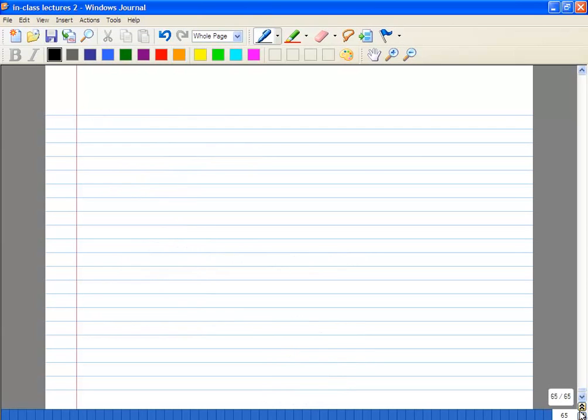Now, other general rules of thumb. We talked about some of these last class. Same W by L for the cascode, and gate equals VDD.